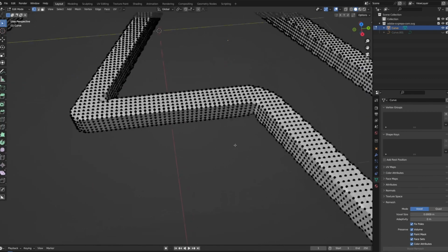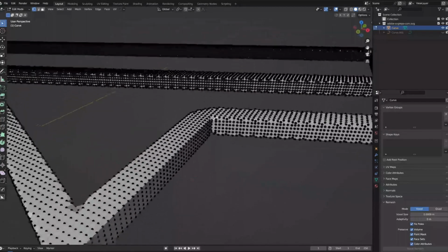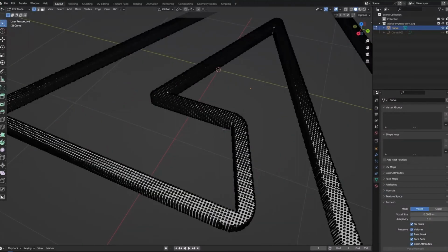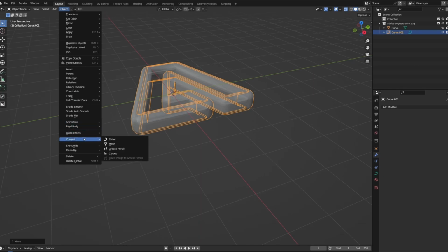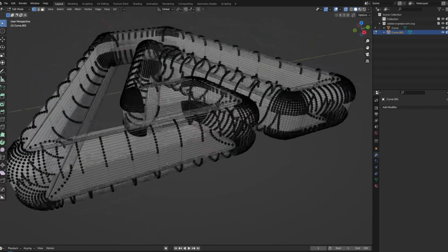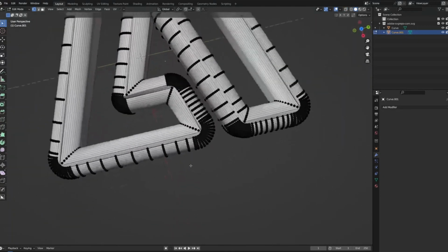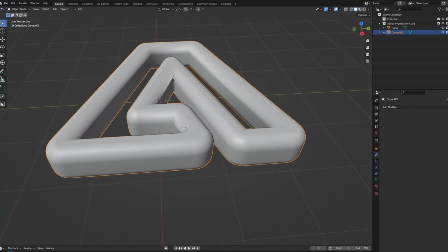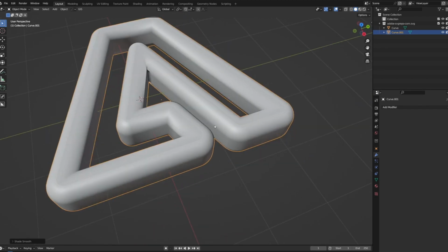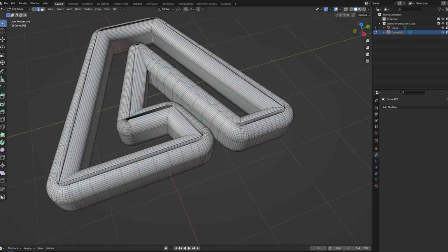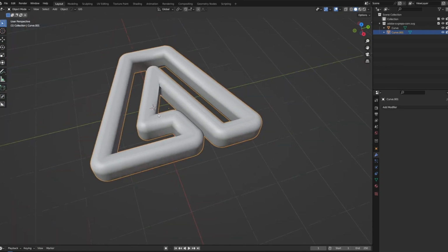You can see now that the remesh feature did a really decent job and the topology is way better than before. Let's continue with selecting the bigger logo and converting it to the mesh as well. Now, since we used the bevel in the curve properties before we converted the curve to mesh, this time the topology is slightly better, but if you pay close attention, there are some bars that are denser and we can still see some triangles. We will fix that in a moment.